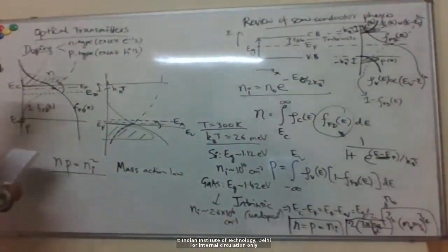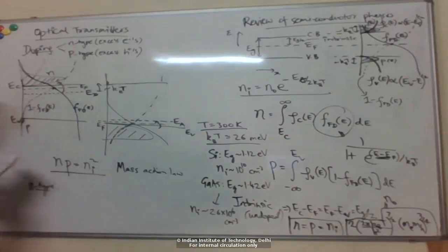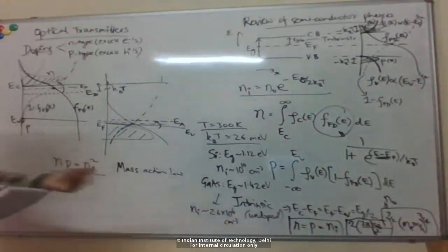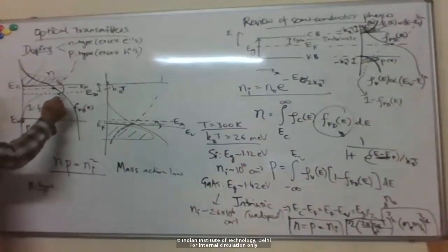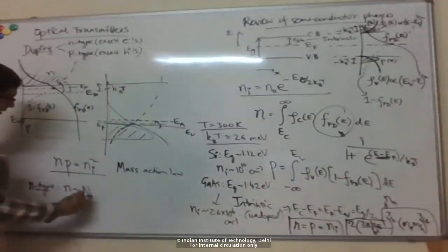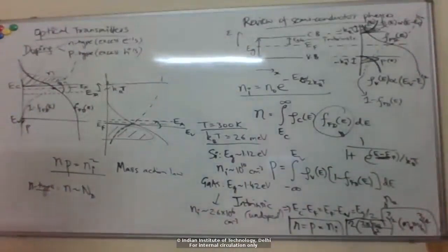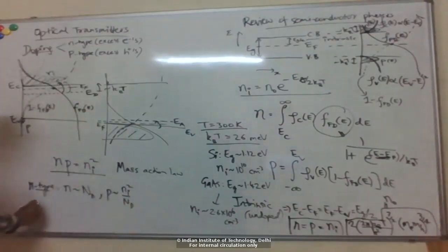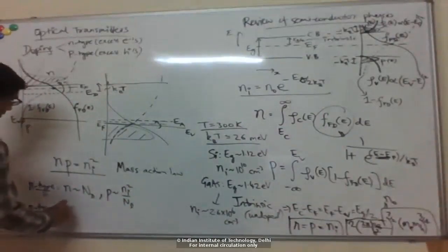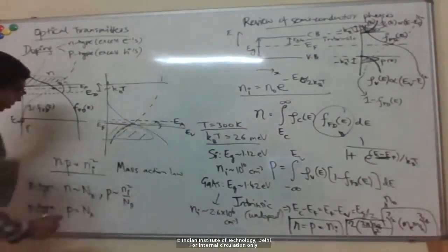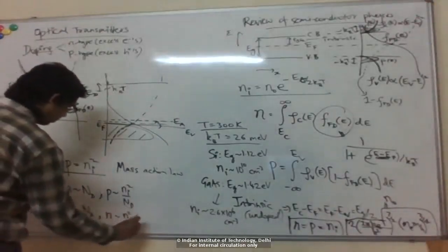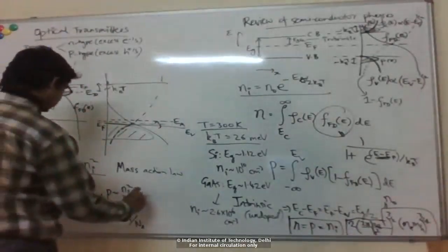Okay, and basically for n-type, the number of electrons roughly becomes equal to the doping, the concentration of the dopant atoms that we add. You can almost imagine that each dopant atom is releasing one electron here. Okay, so basically the number of electrons here is roughly just the dopant concentration. Okay, and so p will be, you can see, right, and for p-type, p will be roughly, again, the concentration of the dopant, which is the acceptor concentration, and then n. Okay, so of course here,